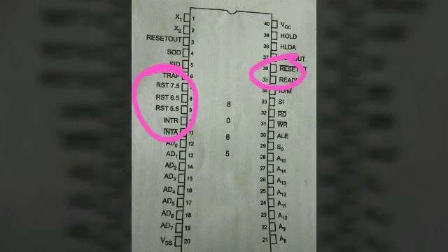Interrupt signals. The 8085 processor provides 5 interrupt signals that are used to interrupt a program execution. These signals are INTR, that is nothing but interrupt request, RST 7.5, RST 6.5, RST 5.5, that is restart interrupt 7.5, 6.5, 5.5, and TRAP, that is the non-maskable interrupt. The processor provides one acknowledge signal for the interrupt, namely INTA bar. It is an active low signal to indicate the processor has acknowledged an interrupt.